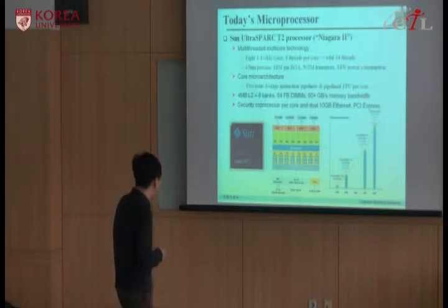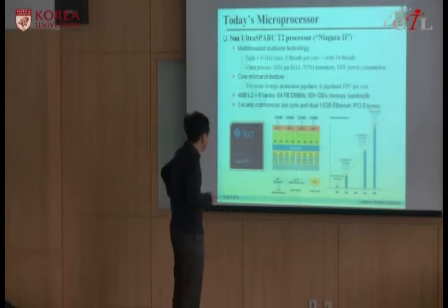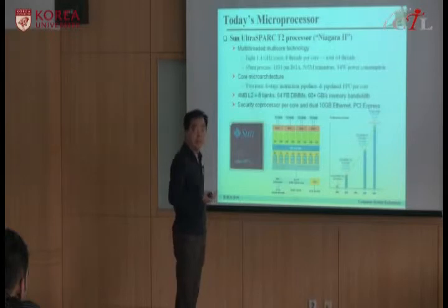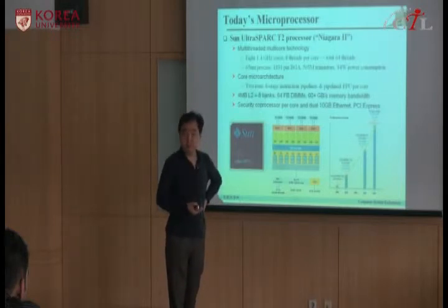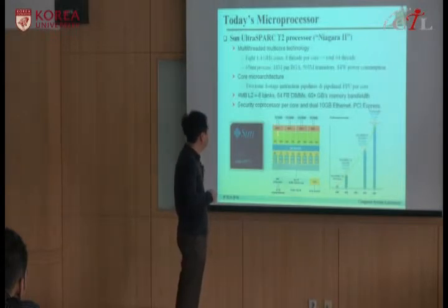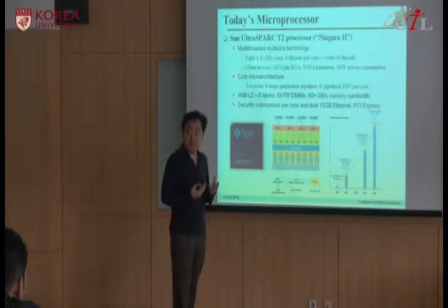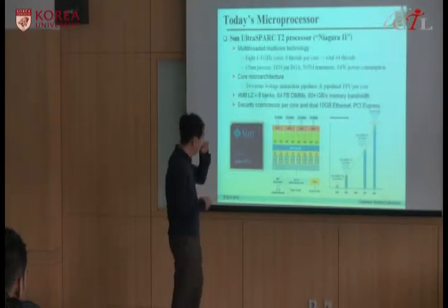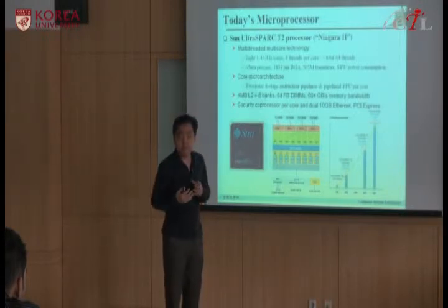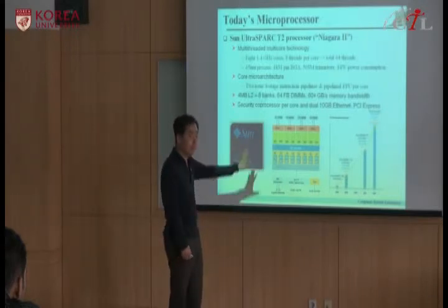So here you have these 8 processor cores, and you have a full crossbar network because they avoid bus technology. It's not scalable with multi-core. So crossbars and L2, and crossbar is also not scalable, but it's a very expensive design. And memory controllers are already integrated into the CPU chip, which is now a trend in i7. This technology moved to PC, but this is for servers.